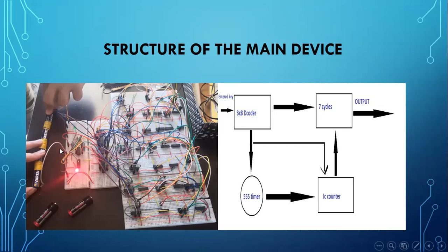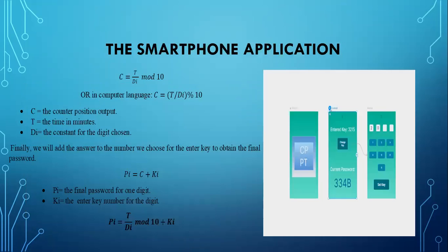So it's impossible to see with the eyes the LED lighting red and green in 0.1 second, but that's how it's going to be. It's going to light green only for 0.1 second, and the rest is going to be 0.9 seconds. If we have a higher value of capacitor and resistor, we're going to have a larger time cycle, and we would see the difference when we see the green lighting. And that was about the main part.